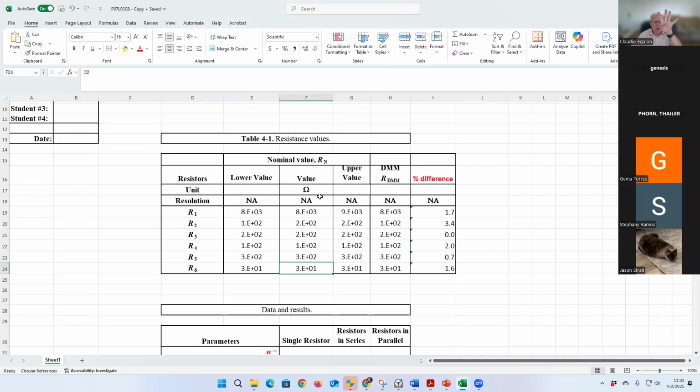My resistors usually have 4 color codes. The first color represents the first digit of the resistance value. The second color represents the second digit of the resistance value. The third color represents the multiplicative power that you have to multiply for the resistance. And the last color represents the percentage difference that the manufacturer has for the resistor itself.